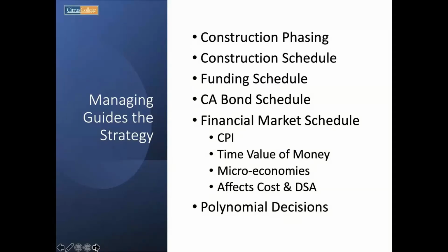So we started doing some thinking, and one of the things that did come to mind is, obviously, we're an old campus, over 100 years old. One of the things that came up was the fuel gas infrastructure. We have a number of materials out there, all of them were code compliant at the time, but as time goes by, you have a new code phase coming in every 3 years. Technology changes on the material science side. To make a long story short, our fuel gas infrastructure probably has at least 3 different materials on the piping side. Some of it's steel, some of it's PVC, some of it's HDPE.